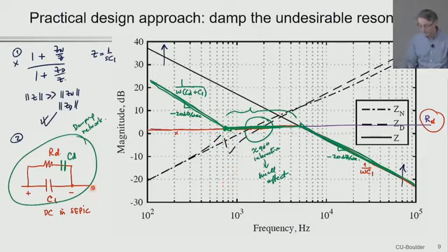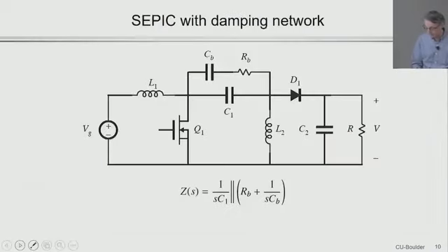Okay. All right. Now let's see what happens when we put this inside the circuit. So here is that damping network, fairly common, by the way, in the SEPIC or Cuk type design. Things actually get a little bit better further when you include ESR of the capacitors. That also tends to damp the resonances somewhat, but you don't want to really count on ESR to solve your problem.